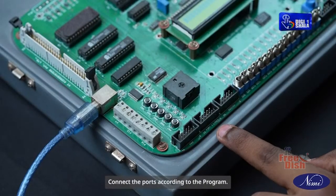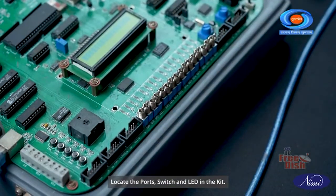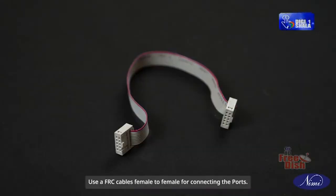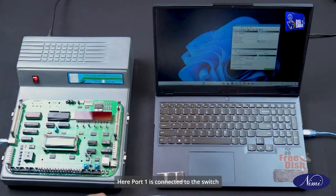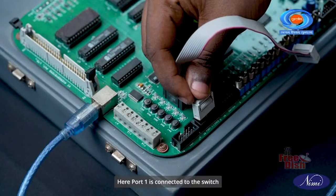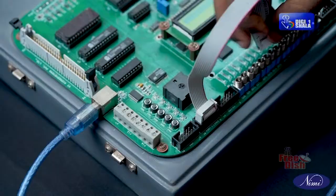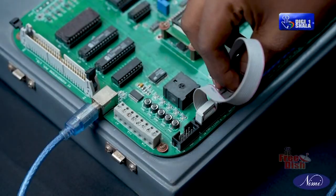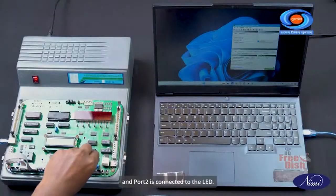Connect the ports according to the program. Locate the ports, switch and LED in the kit. Use FRC cables, female to female, for connecting the ports. Here, port 1 is connected to the switch and port 2 is connected to the LED.